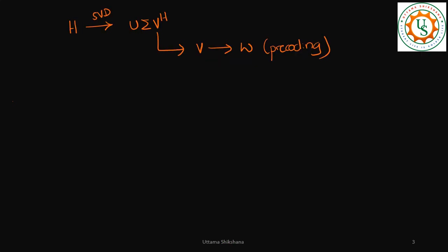However, what was our intention? Why were we using it like this? Basically, we wanted to nullify the effects of the channel, and we need to ensure that at the receiver, the signals across the antennas are separated out. There shouldn't be any interference of the signal from one antenna with the other antenna. That was the goal, right? Once we use the pre-coding matrix, we expect that some effects of the channel are nullified, and at the receiver, if we do receive beamforming, then we get the separated signals across the antennas.